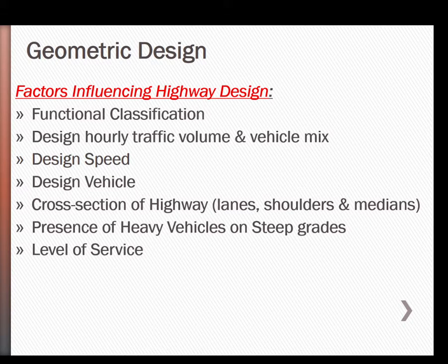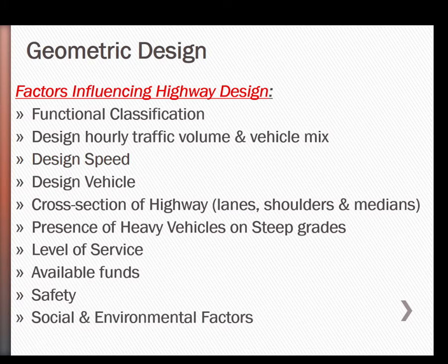The level of service: how convenient and comfortable you want the drivers to be, with fewer delays and higher speeds, which gives me a better level of service. Funds, money, is also one huge factor that influences your highway design, and it also comes from functional classification. The higher level the road, the more expensive it is, and that's very obvious. And safety is something you also want to use in design. Finally, we have the environmental and social factors.